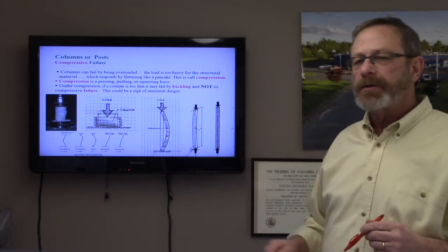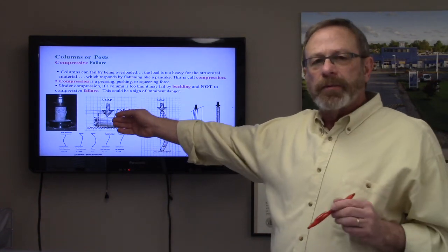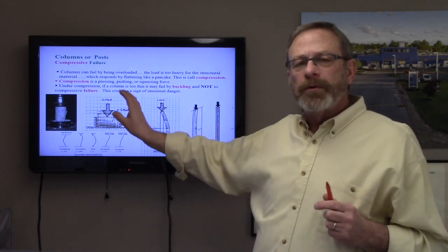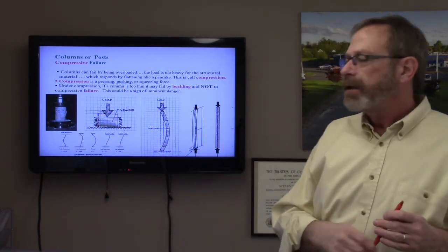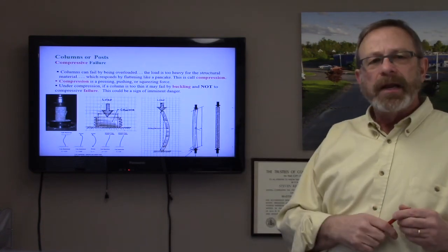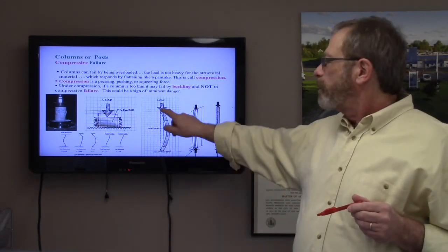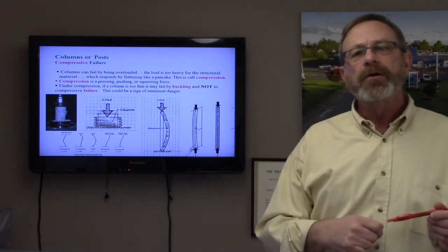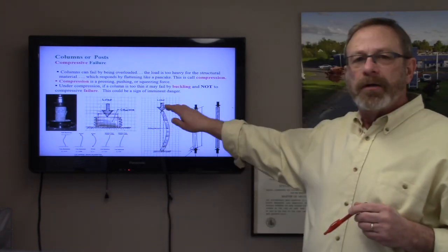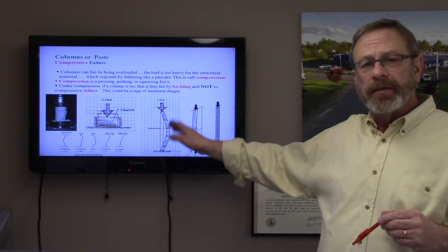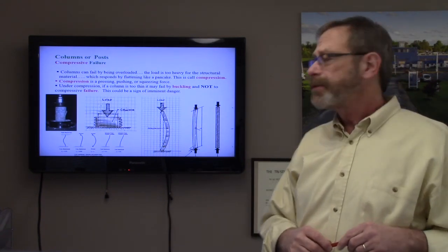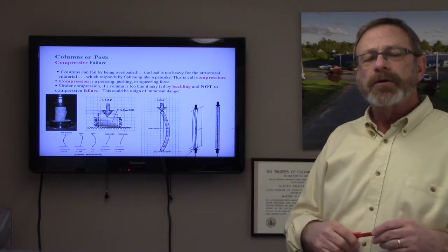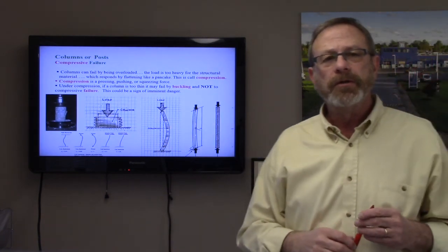Some of the other implications that we talk about: the concrete is going to compress, probably imperceptibly, but when the load is removed, it will return back to its original state. Another situation where you might have too much compression could result in buckling. You can imagine that increased buckling here would eventually result in failure of that column. More load, more buckling, warning signs, then finally cataclysmic collapse.